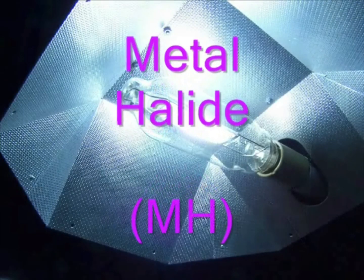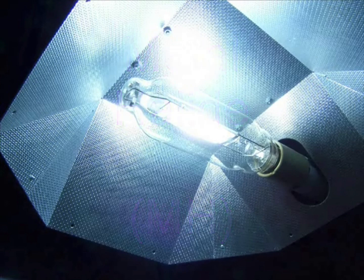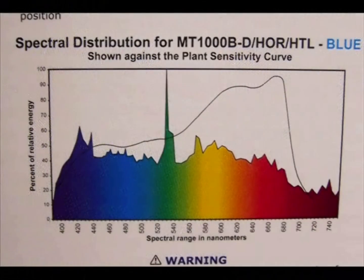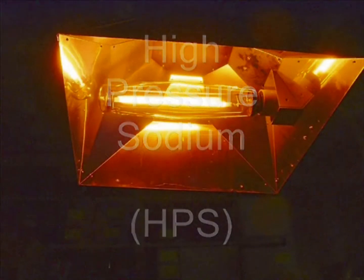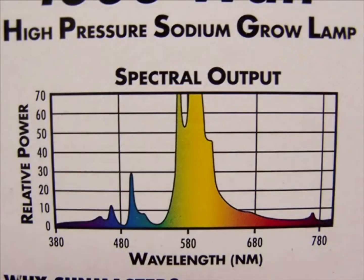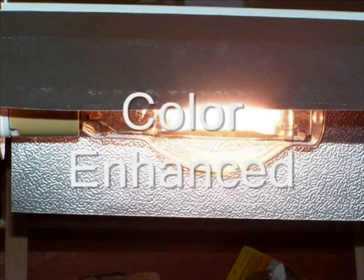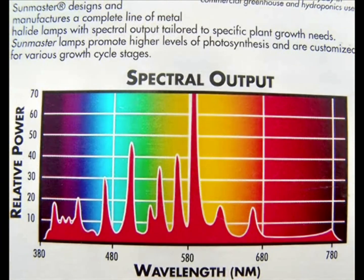One of the most popular HID grow lights is the metal halide. The metal halide is a full spectrum bulb that provides adequate blue frequencies, excellent for the vegetative growth stage. Also very popular, the high-pressure sodium light is a full spectrum light as well, providing intense yellow to red frequencies, enabling flowering and fruit production. There are several color-enhanced HID lights available that provide both blue and red frequencies that will work well for the entire growth cycle for many plants.